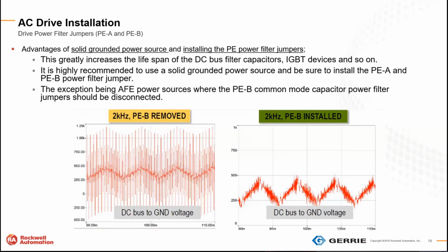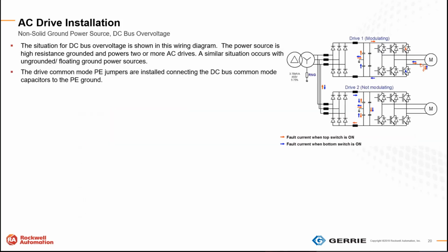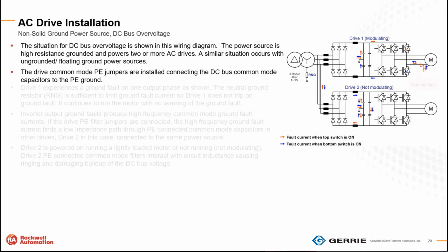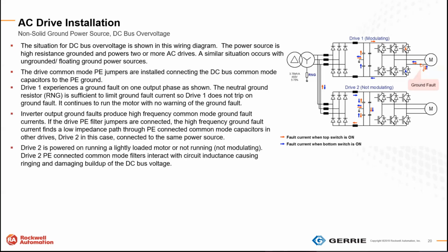Depending on how long it's going to take to fail, it depends on how hard the drive's working, that type of thing. It's important to get the jumpers in the right position, and it should be something that you take heed of and write right into your operational procedures. Oftentimes when we go in to do any service work on any drives, any PMs, one of the things we do is always make sure the jumpers are in the right position, because over time it can cause catastrophic failure.